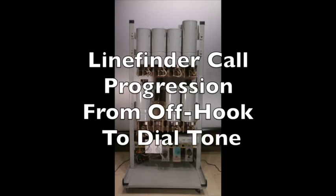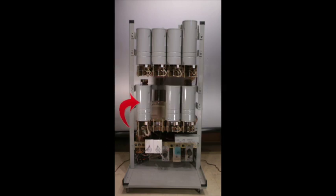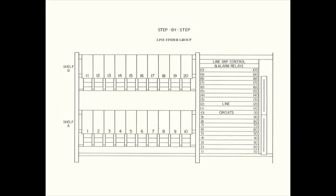My step-by-step demonstration unit only has one line finder, so I have no actual equipment to demonstrate line finder preference selection processes or subgroup operations, so I will do this using diagrams. For the purposes of this video, we are going to assume that I have a line finder group equipped with 20 line finders. My demonstration unit line finder will be line finder number 1 in this group. I am going to originate a call from telephone set Pennsylvania 65000. It is assigned to line circuit terminal 00 in the line finder group.